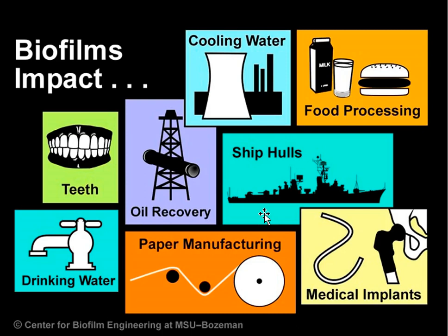In this case, the methods available are paints with some type of toxic chemical to keep the microorganisms away. Copper-based is the most popular, but again, restrictions on how much you can put on and causing local pollution and such make it difficult to keep the ship hull clean and comply with environmental regulations.